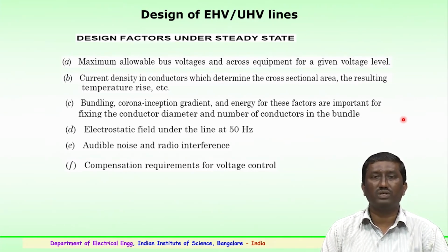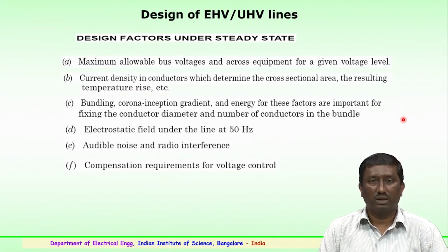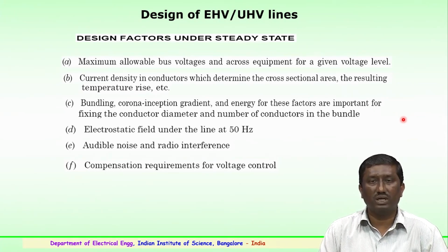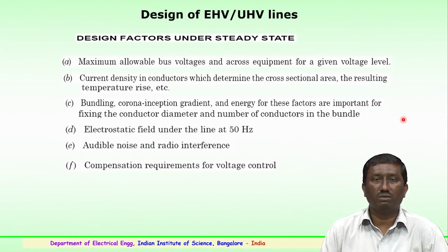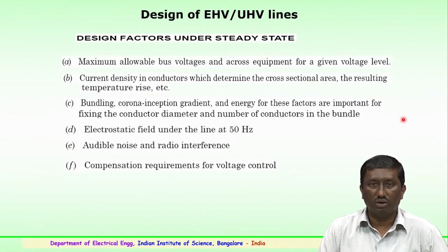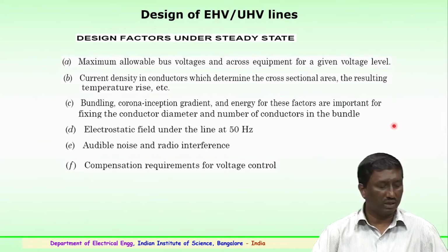For a radio interference of 400 kilovolts and above, 1000 microvolts or 56 dB is the tolerable limit, and it should not increase more than 60 dB; that is, 1000 microvolts is very important. So, these conditions have to be considered for the design of the conductors or the hardware which are being used for the towers.